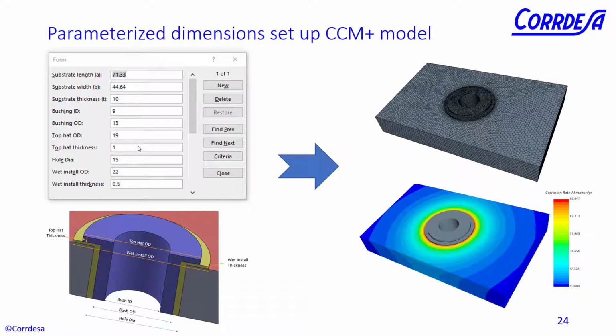So a materials process engineer can run the GUI on the left hand side, and they don't have to create a computational mesh on the right. That's done automatically. They simply get a report of the corrosion rate of this fixture system, or in this case a bushing. Very quick. And now you've not got this constraint of a 1-to-1 anode to cathode area ratio. Or indeed, you can also do different electrolyte thicknesses.